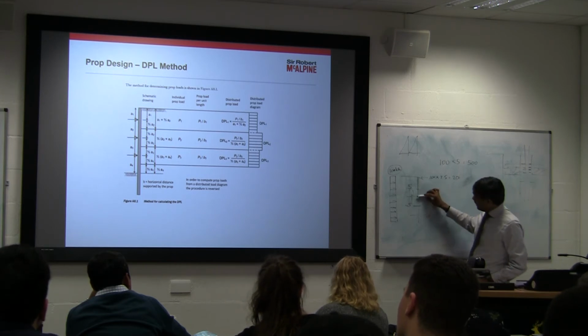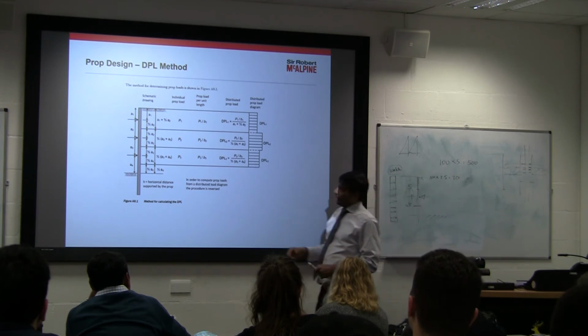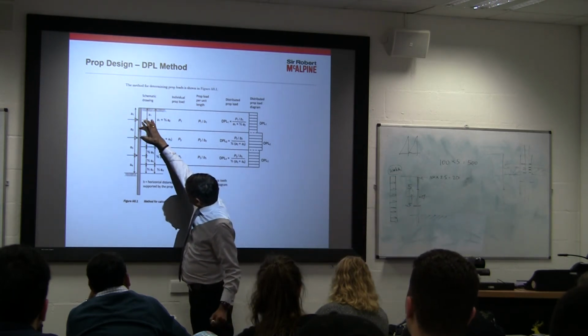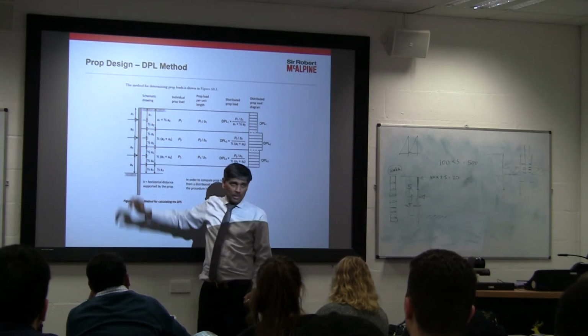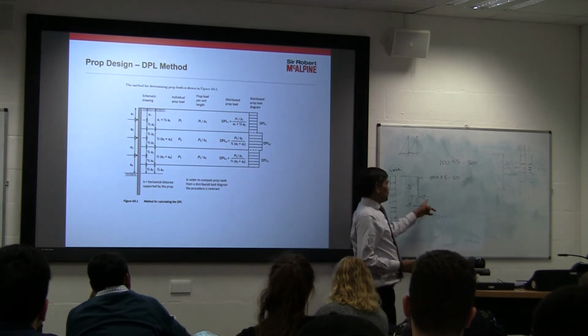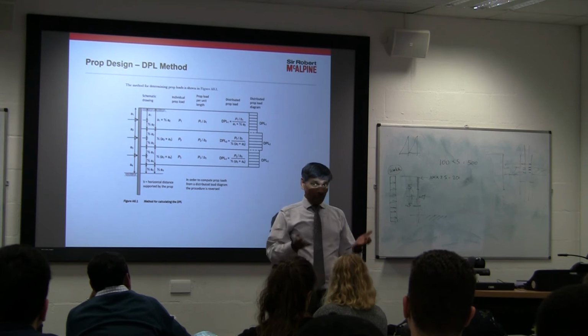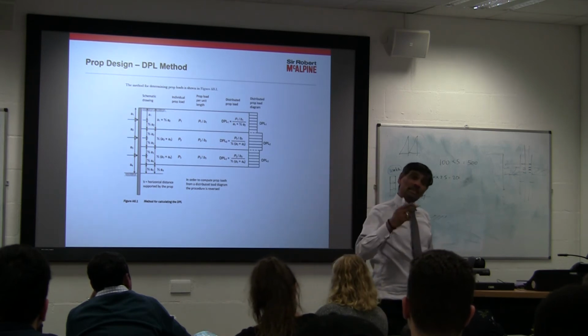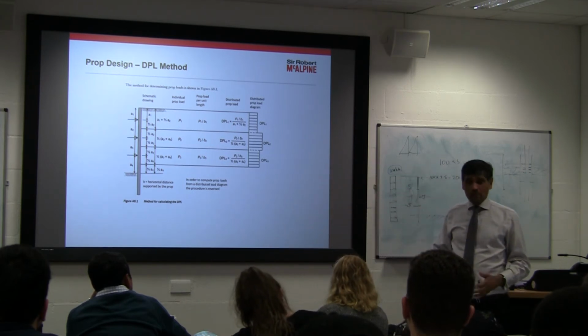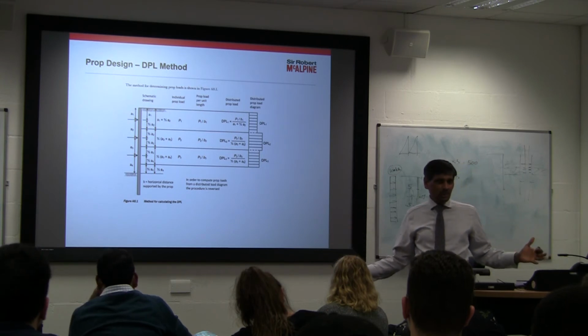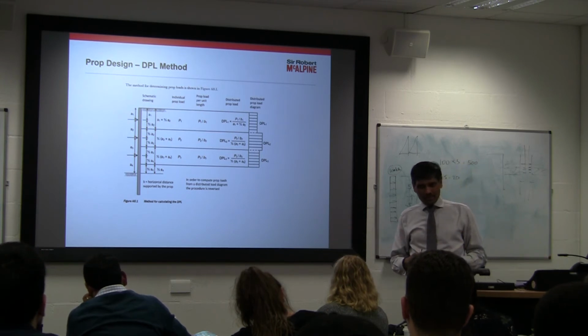Because the catchment area of that prop is very high. So you get some load half this way, so that's the catchment area. So once you start introducing a second level of props and third level props, the prop load keeps going up. So that's another thing that you have to think about. So the prop size, if the load goes up, again the prop size is very big. Again you have to think how to take it out.